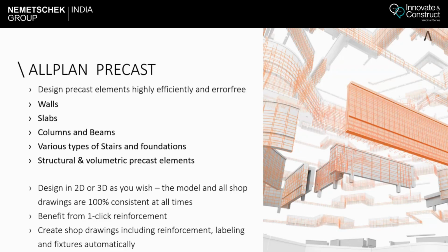So whatever changes we are doing in the drawing, the same changes will get updated in the model, and vice versa. Let's say we make some changes in the model, the same changes will automatically get updated in the drawings as well. So with the tools, we can create shop drawings and add rebars. To start with, we can add concrete geometry, then we can add reinforcement. Once the reinforcement is done, we can add fixtures to it, and after the fixtures, we can go to the drawings for creating the labeling and dimensioning part.